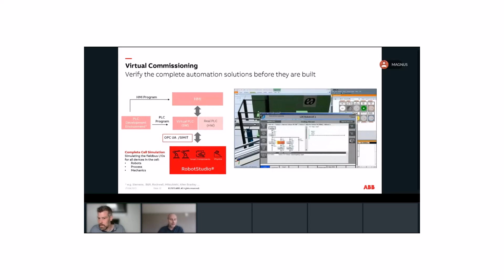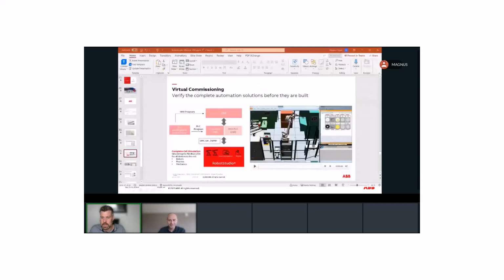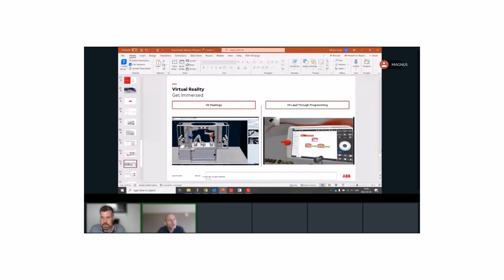Super, thank you. Moving along here, Lucas wants to know, how about offsets and reltools? Will they also be visible in the simulation in this new RobotStudio version? No, it will not, unfortunately. This is a tricky thing, especially when it comes to offs and reltools and so forth, because it is a little bit of a challenge to do that, but it has been on the wish list for a long time.